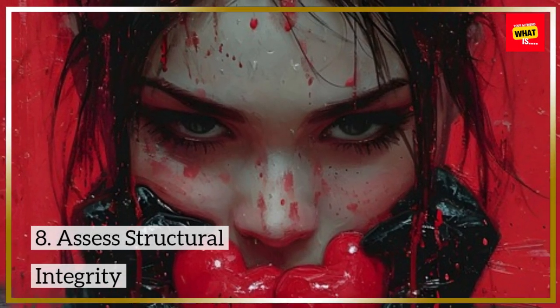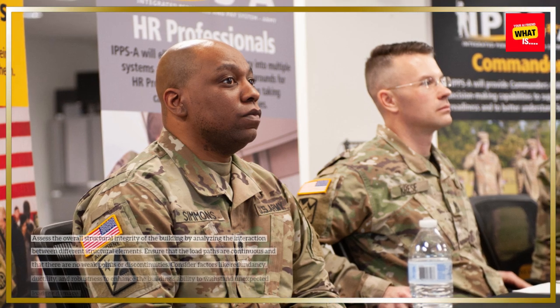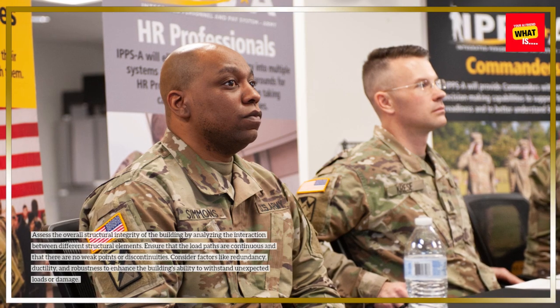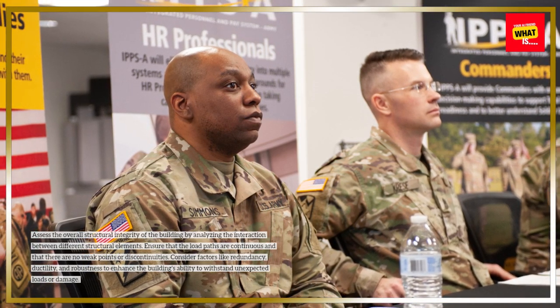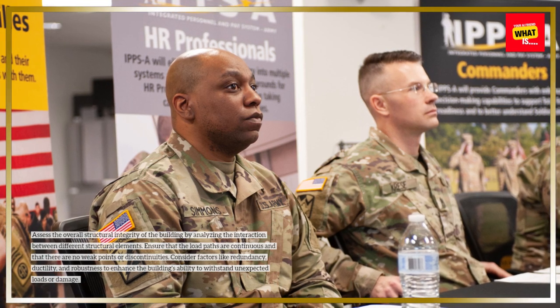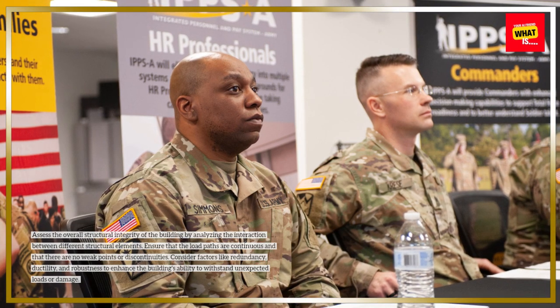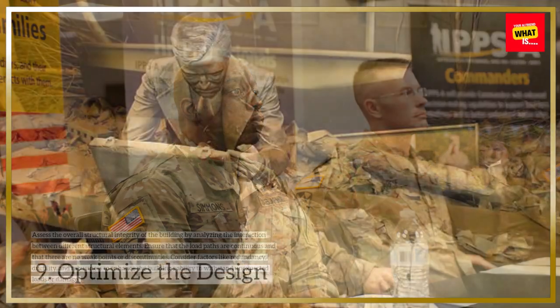8. Assess structural integrity. Assess the overall structural integrity of the building by analyzing the interaction between different structural elements. Ensure that the load paths are continuous and that there are no weak points or discontinuities. Consider factors like redundancy, ductility, and robustness to enhance the building's ability to withstand unexpected loads or damage.